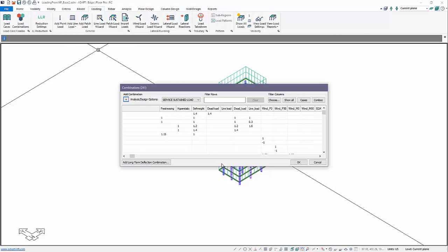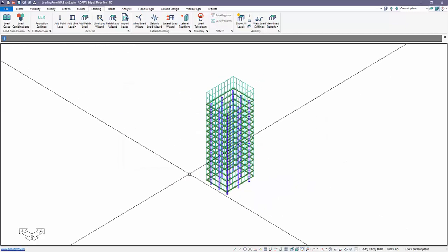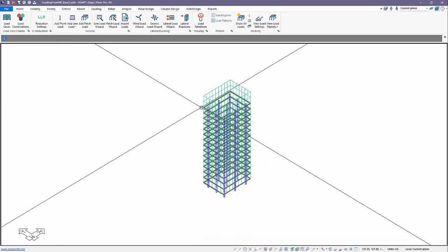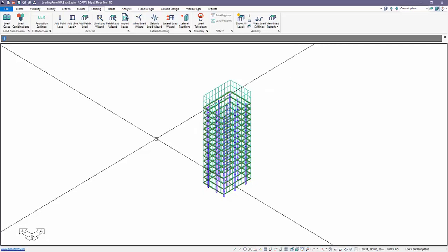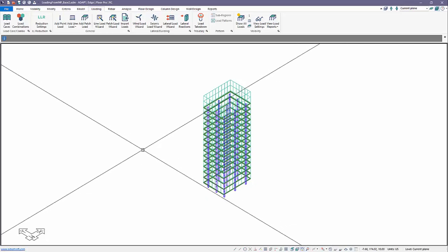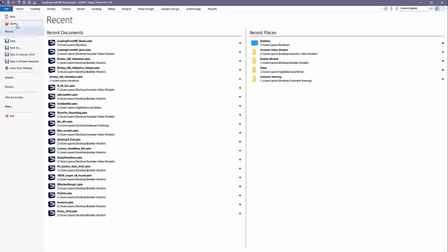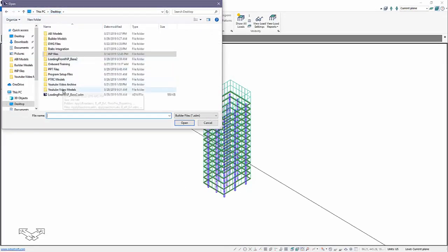Now, if we want this to be imported with mapping of proper load cases rather than duplicating the load case name, then we have to actually have what we'll consider a dummy load for dead and live in the actual INP file that we import, so that we can map those load cases into this model. So we're going to start over here. We're going to build just a few combinations because the master ACI file that I was using doesn't have the data inside of it for reactions. I can't really use that to show this. So we're going to go back and open up my base model.